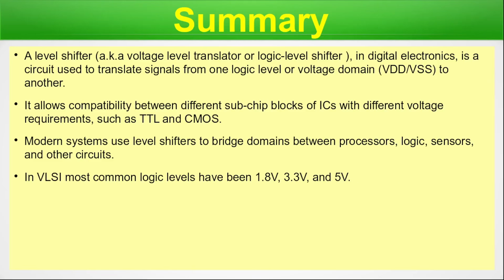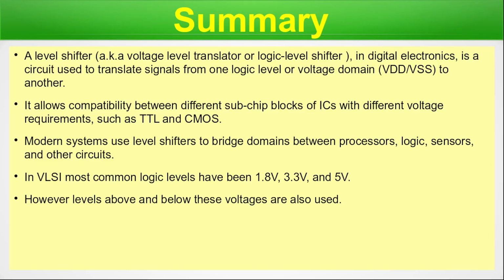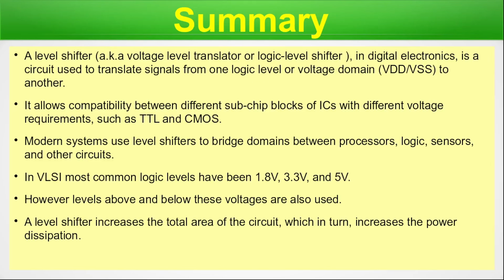In VLSI, the most common logic levels have been 1.8 volt, 3.3 volt, and 5 volt. There could be other variations. You must not have only these values in your mind, so be open-minded at this point. Levels above and below these voltages are also used. A level shifter increases the total area of the circuit, which in turn increases the power dissipation. So this is a drawback of using a level shifter inside a chip.